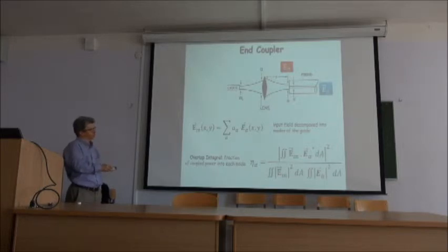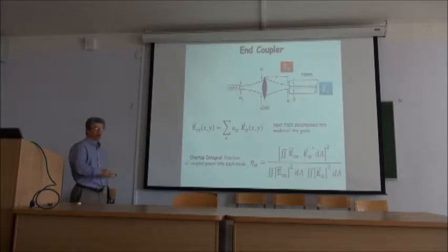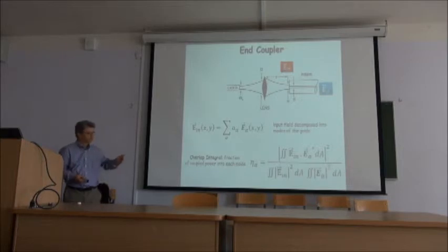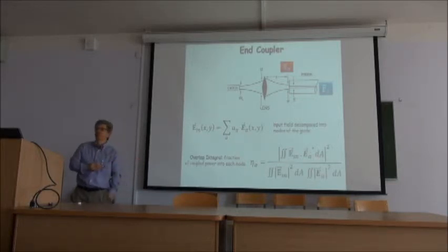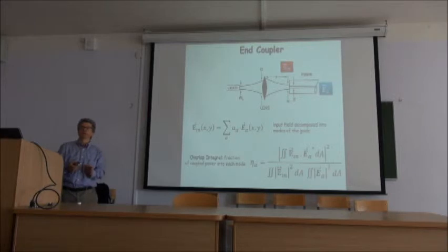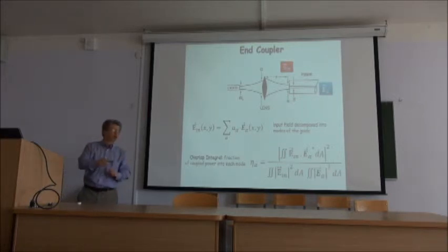On the other hand, when you have a single mode, if you want to maximize the power that you are coupling, you want to maximize this overlap, and to maximize that, you want a replica of your incident field to replicate the mode that you have on your fiber. You don't want that to be much larger or much smaller, you want that to be a replica.